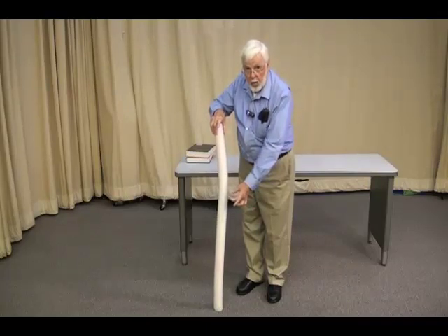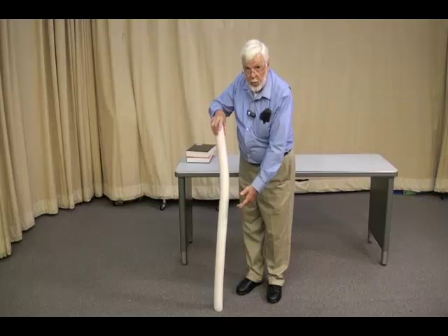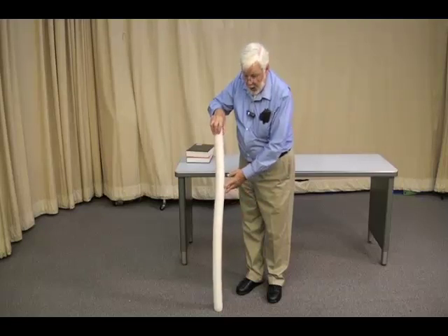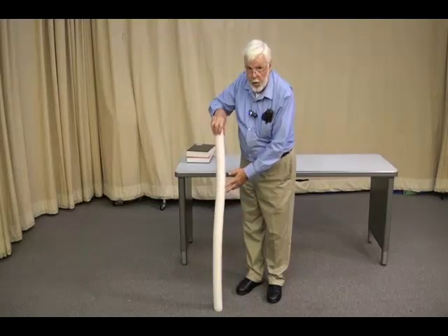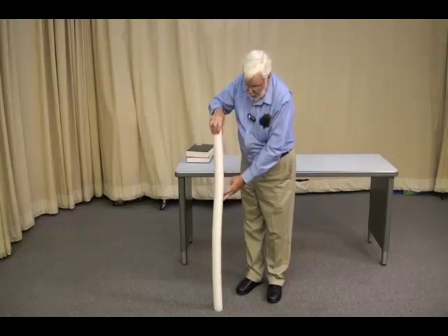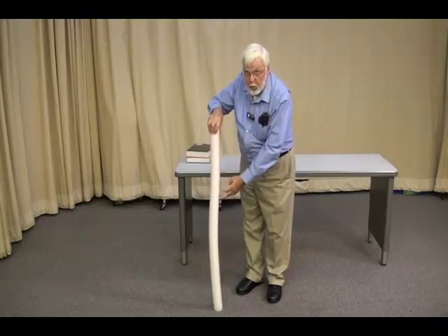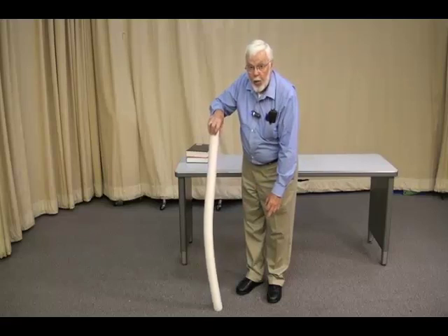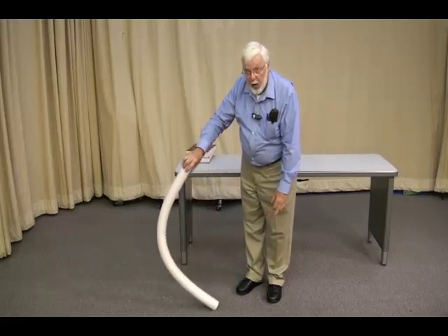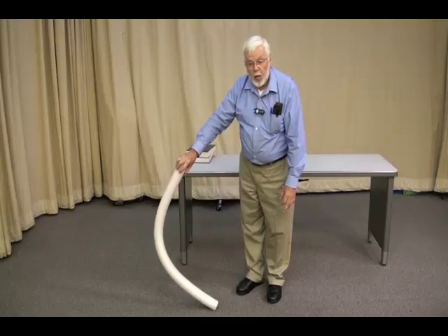That gives a moment arm that increases the bending moment, and that's a case of positive feedback. So as that deflection increases, it gets to a critical point where the bending moment increases without limit, and the thing will go to failure.